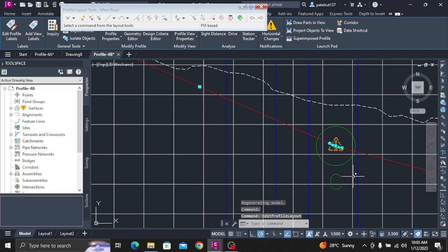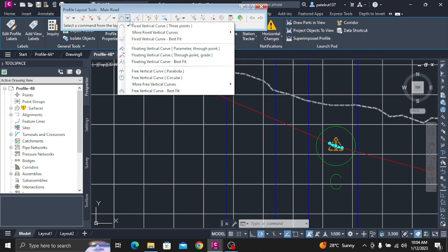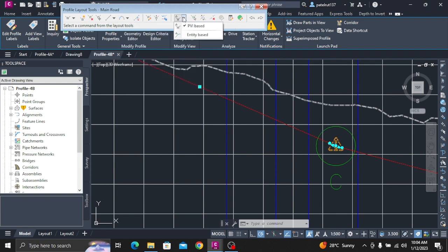Click Edit Current Selection. In the Profile View Style dialog box, examine the contents of the various tabs to see the many settings that can be included in a style definition. For example, on the Title Annotation tab, you can change the format and location of the Profile View title. On the Display tab, you can turn various parts of the Profile View on and off. Click Cancel, and then click OK to close the Profile View Properties dialog box.